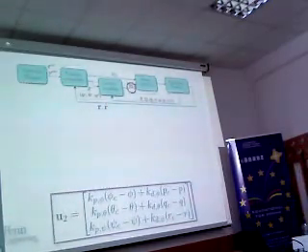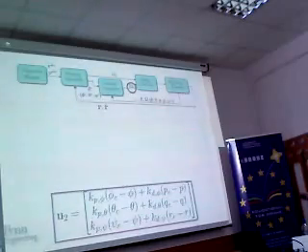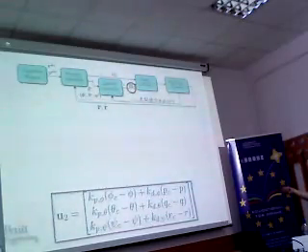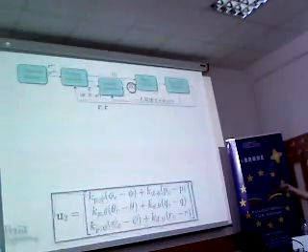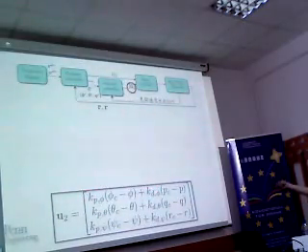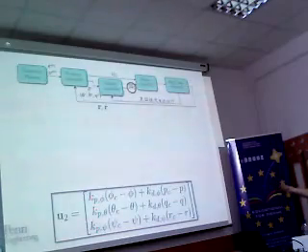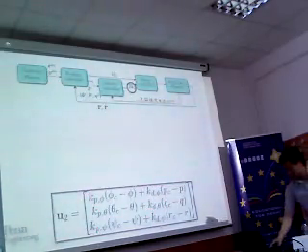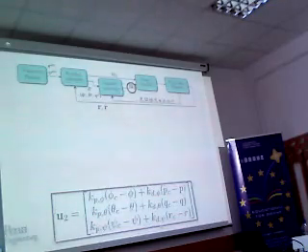And you can see here for each parameter, for roll, for pitch, and for yaw, you have its own KP and KD. It means that here we have 3 KPs and 3 KDs for each of the roll, pitch, and yaw parameters. Feedback are the actual roll, pitch, and yaw angles, and their derivatives.